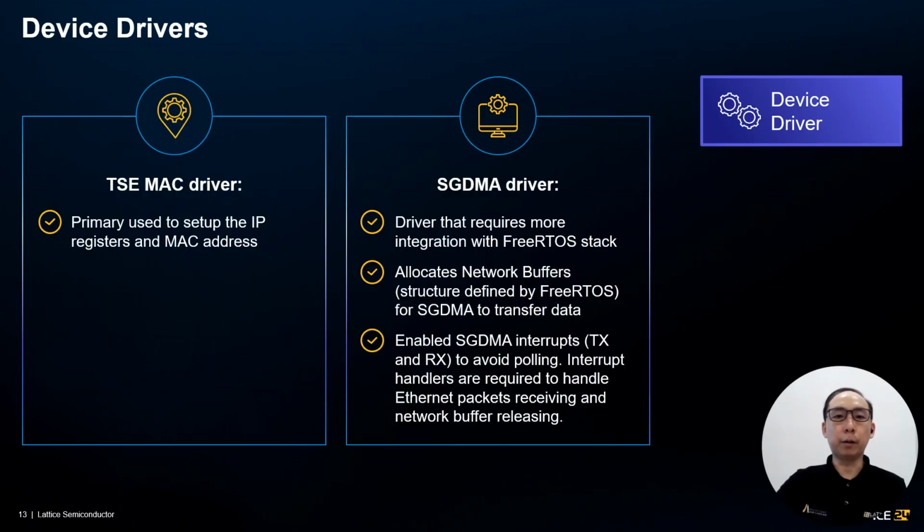Now, let us look at more details on each of the software layers described previously. First, let's start with the device drivers. The main drivers used in this software example are the Ethernet driver and the SGDMA driver. The Ethernet driver is primarily used to set up the IP registers and also the MAC address in the controller itself.